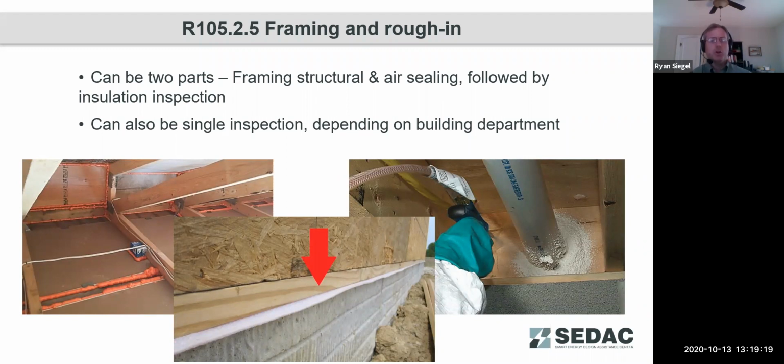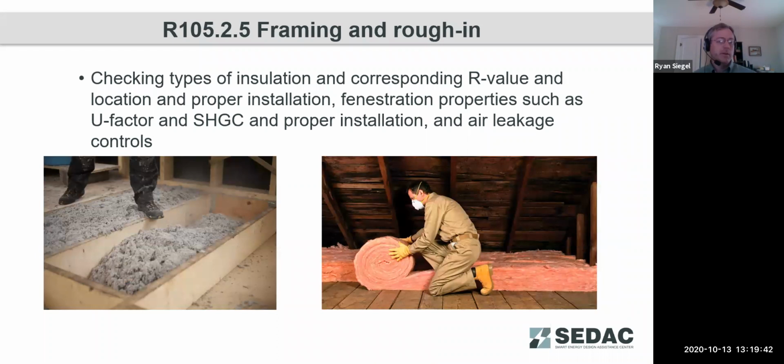Probably a good practice is to have these as separate inspections, so that way it's easier to identify issues with air sealing before they get covered up by insulation. So again, do check with your local building department as far as the order and locations in which they prefer to occur.